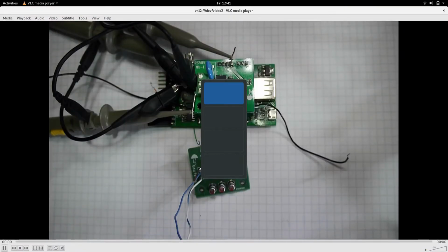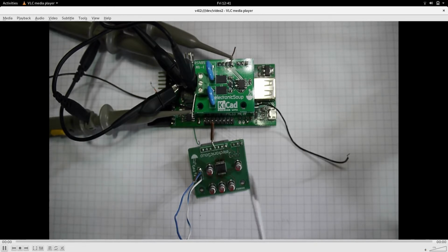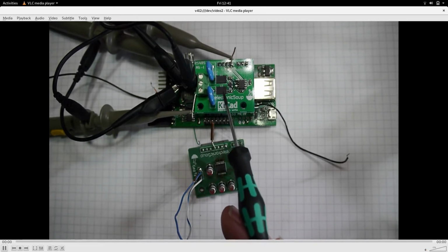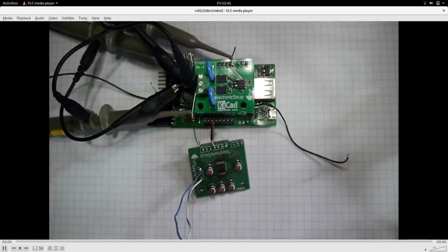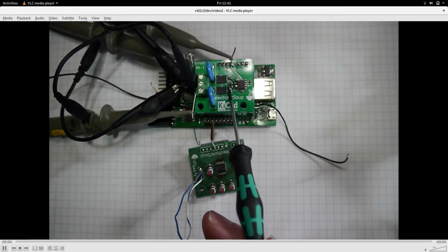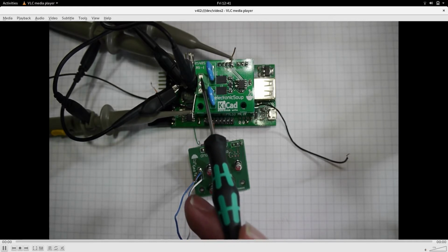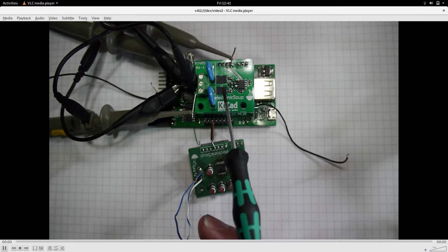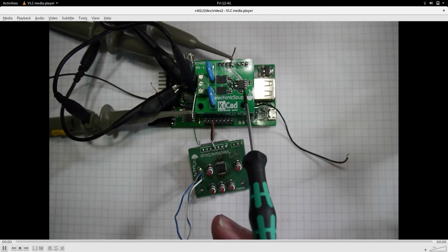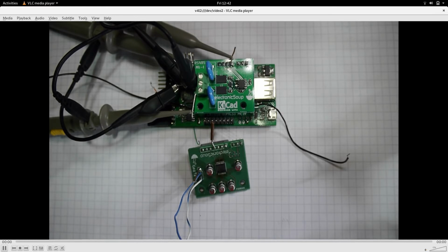And if you look at the actual board, most of this is TVS, transient voltage suppression. Because RS485 goes into a lot of industrial noisy environments where there is a lot of electrical noise, and you will get voltage spikes, we know we're going to get voltage spikes, or we expect them, then we've got transient voltage suppressors built into our circuit and varistors to try and minimize both on the A and the B channel. A is on top, B is on the bottom, but on both those channels we're trying to suppress the noise, and then it's fed into our transceiver. And that's it.